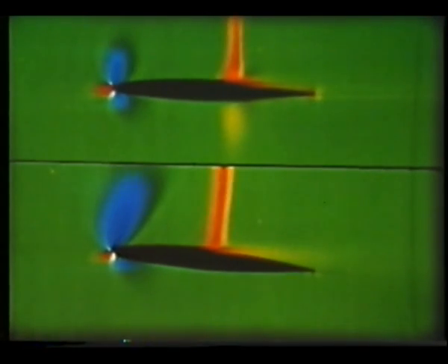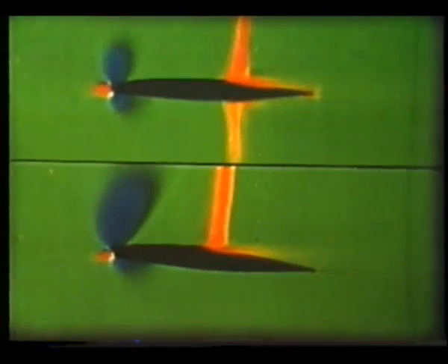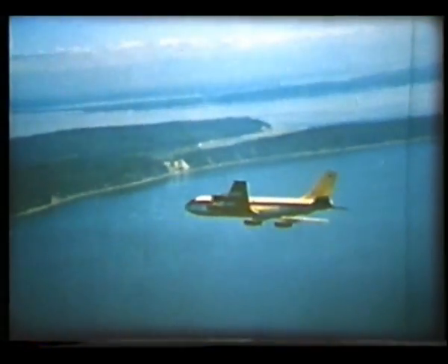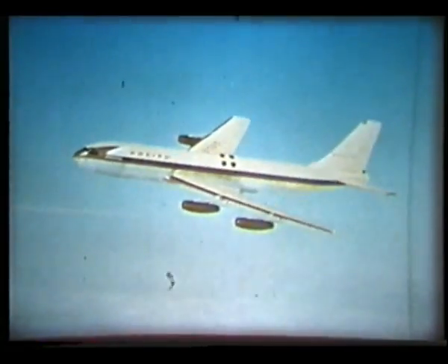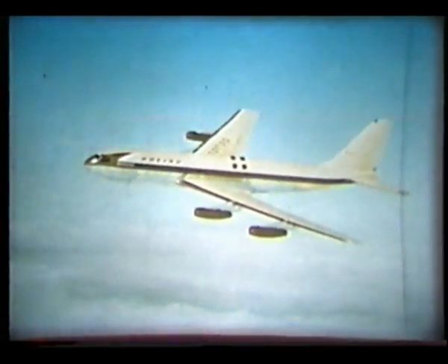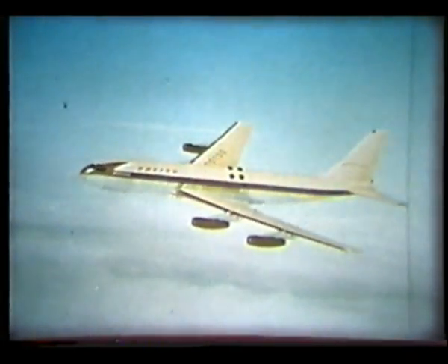How can these troubles be met? In part one, we saw that two design features, thin wings and sweep back, raise the critical Mach number and postpone the shock stall to higher speeds. But exactly the same features, thinness and sweep back, lessen the effect of the shock stall itself.